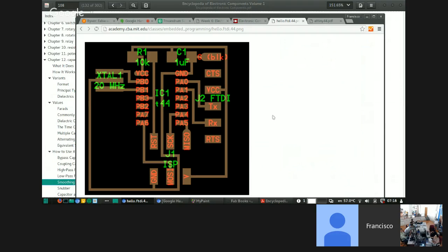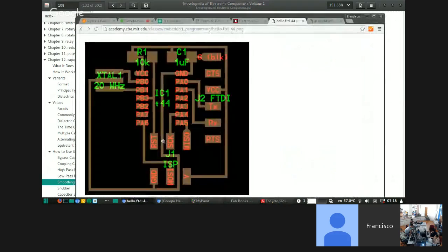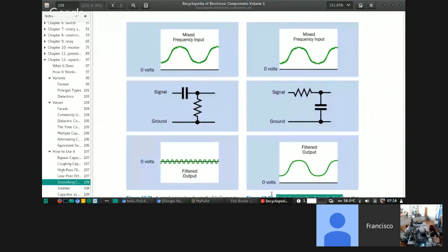Yeah. For this circuit to be like this, you should have the 5 volts and the resistor in here. So you could modify this circuit to have a resistor, to have this filter. Yeah, that's an RC filter. We don't really need that, I mean, right? Do we need that? In our circuit, we don't need an RC filter, something like this.